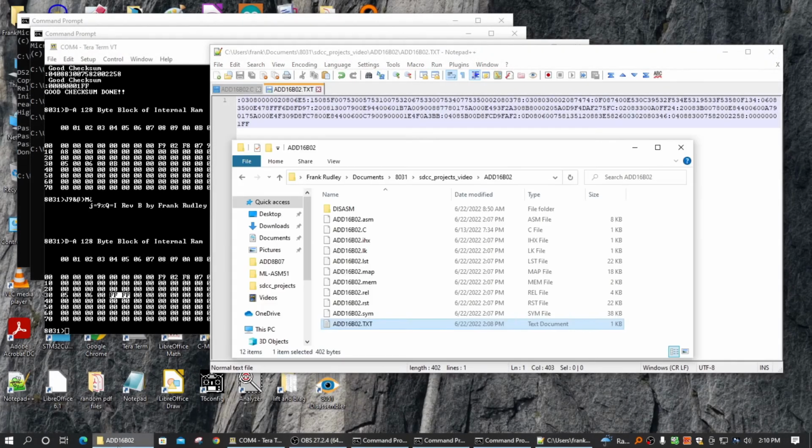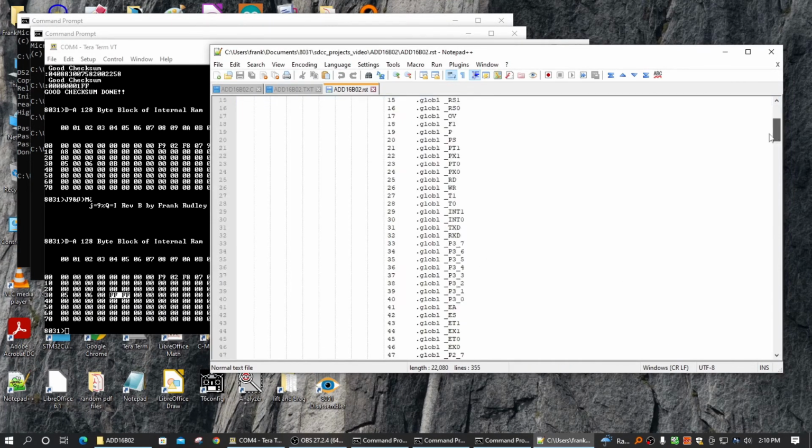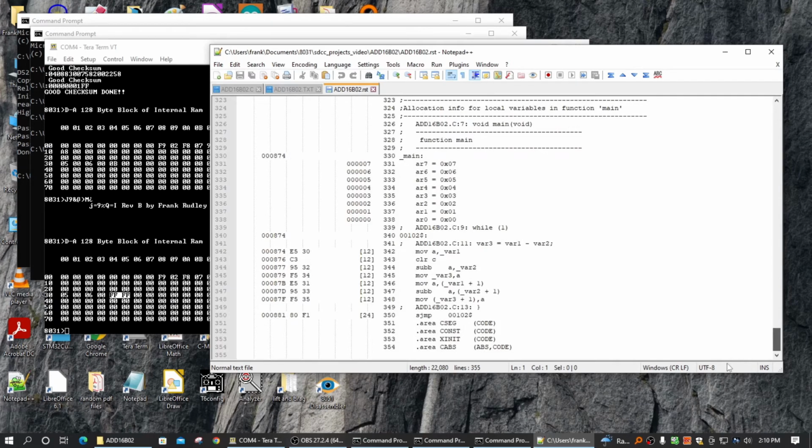So what I want to do now is look at that RST file to see how it does a subtraction for two 16-bit numbers. So you could see it in here. The sequence of operations is somewhat different when you do a subtraction. I believe you have to clear the carry flag first. So you could go through this at your leisure and try to figure out how this thing worked. With these instructions, how does it come up with FF?